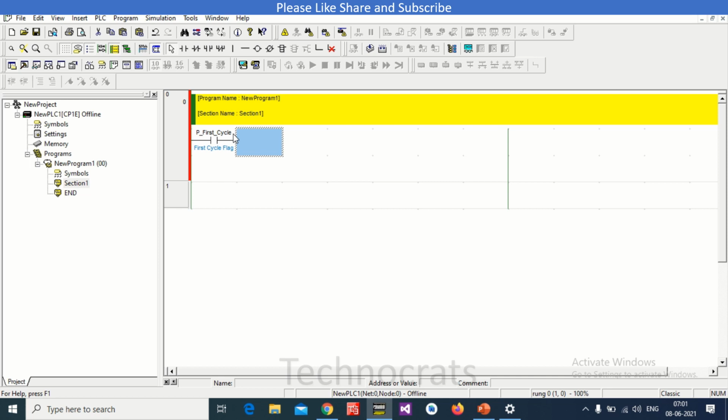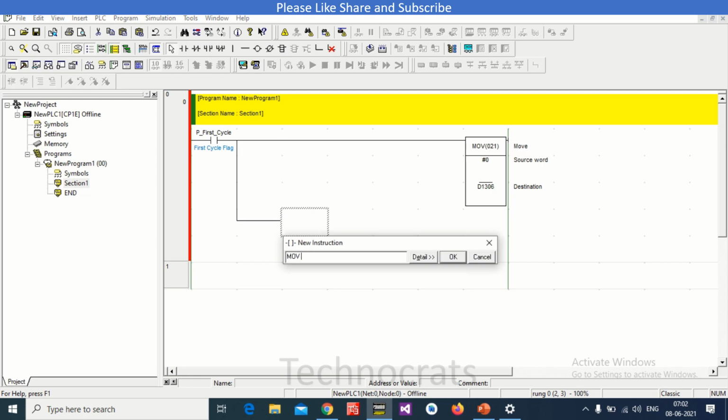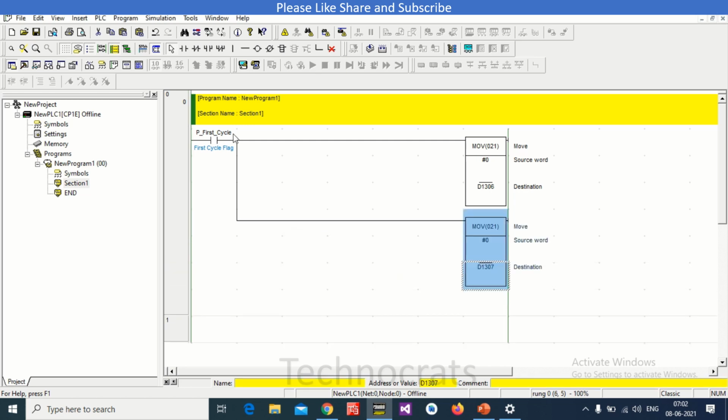So let's start. MOV first. We can use #0 and D1306. Now MOV #0 to D1307, and we will also reset the polling bit of Modbus, that is A641.